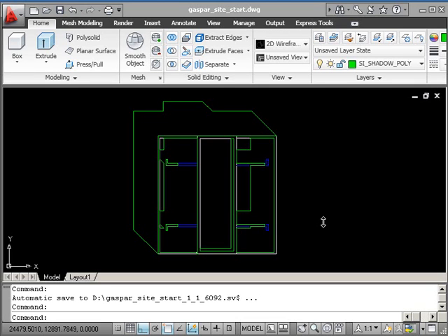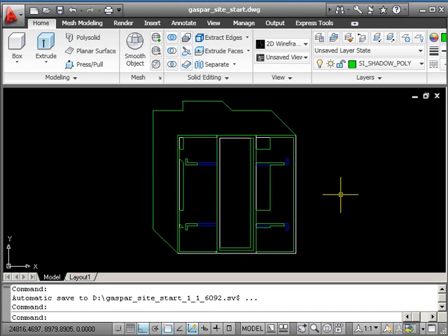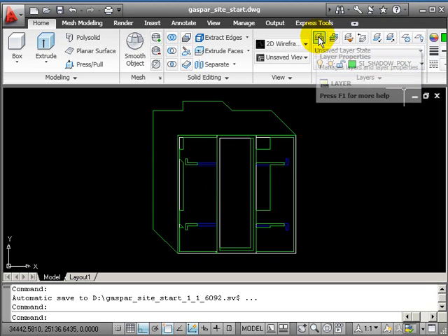Right, we'll finish off the shadowing of this by adding the actual shadows themselves. So I'm going to show you the hatch command. We've used this already slightly on the walls of the house in a previous one, but this time we'll try it a bit more cleverly.